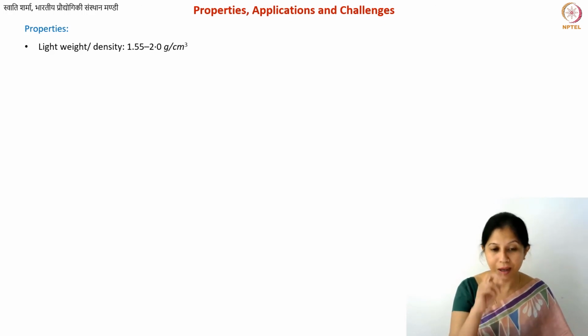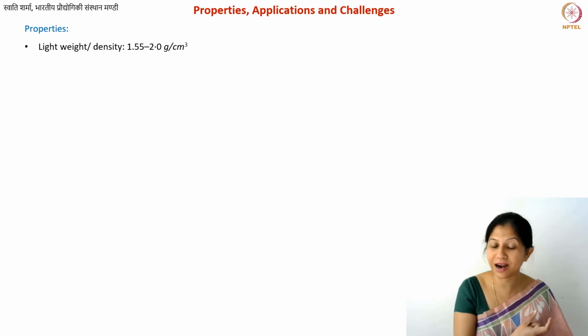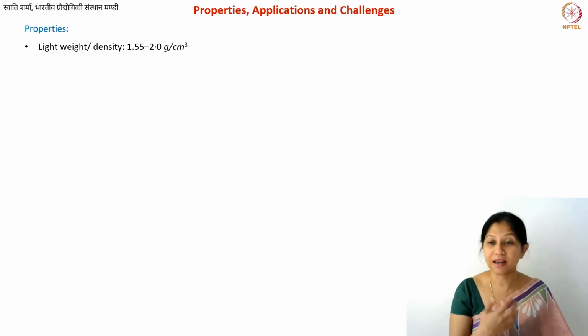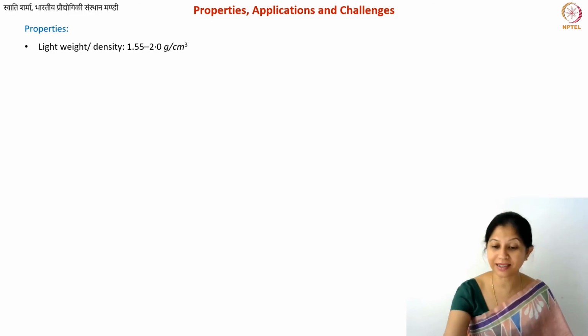because you may not have as much closed porosity, microporosity, as in the case of glass-like carbon, because here you also have different structural components, and you have carbon fibers which already did not have so much microporosity as compared to glass-like carbon. Also, several times you performed the densification. So that is why in this range you will get your densities.